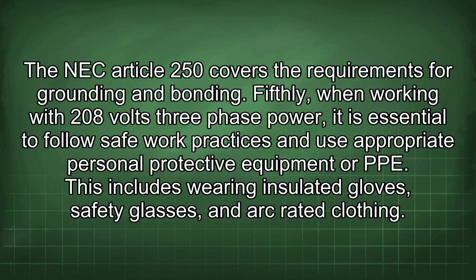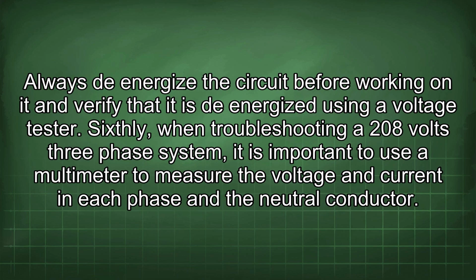Fifthly, when working with 208 volts three-phase power, it is essential to follow safe work practices and use appropriate personal protective equipment or PPE. This includes wearing insulated gloves, safety glasses, and arc-rated clothing. Always de-energize the circuit before working on it and verify that it is de-energized using a voltage tester.